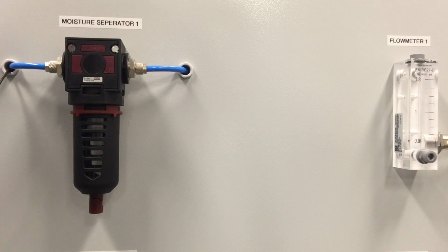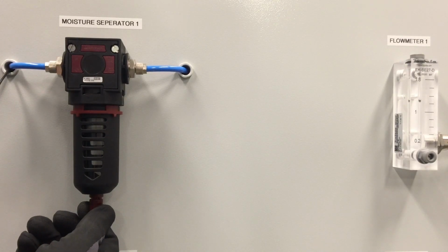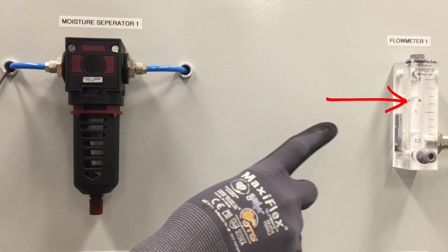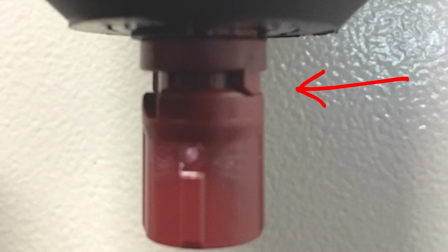A common problem is that the moisture separator is not closed properly enough. Turn the knob at the bottom of the moisture separator a quarter turn, and you will see that the flow meter now has enough flow to be able to conduct a reliable measurement. To make it more clear, in this picture the moisture separator is open. The measuring system cannot perform a reliable measurement. In this picture the moisture separator is closed. This is the right position during measurement.